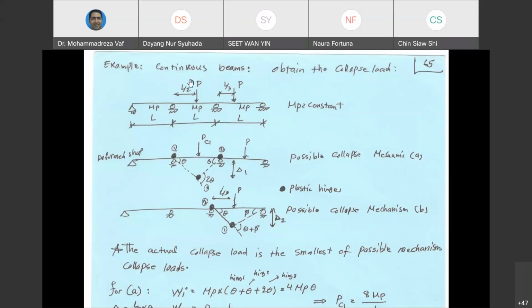So first, we are going to look into the middle span and calculate how much the critical load is going to be for this span. If this span wants to collapse, as we said before, we need to have 3 hinges. These 3 hinges can be plastic hinges, or can be a condition in which we have a roller or pin support. Now, in the middle of the span, although we have 2 roller supports here, the bending moment in this location and this location is not 0, because the beam is continuous. Therefore, if there is going to be a collapse inside this span, there should be 3 plastic hinges. And the location of these plastic hinges is very clear for us because the bending moment at the supports is always maximum. And another location where the bending moment reaches its maximum is the place where the force has been applied to the beam.